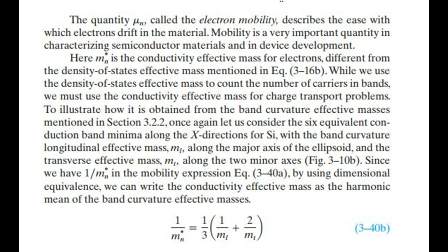Here m*n is the conductivity effective mass for electrons, different from the density of states effective mass mentioned in EQ 316b. While we use the density of states effective mass to count the number of carriers in bands, we must use the conductivity effective mass for charge transport problems.